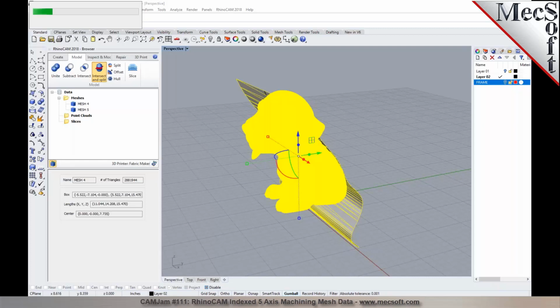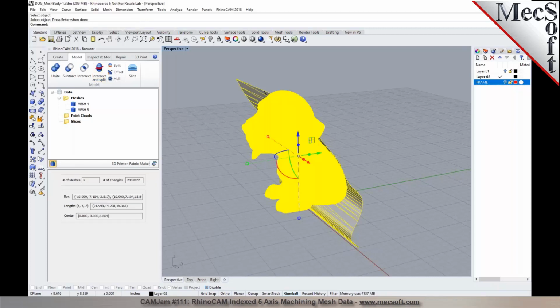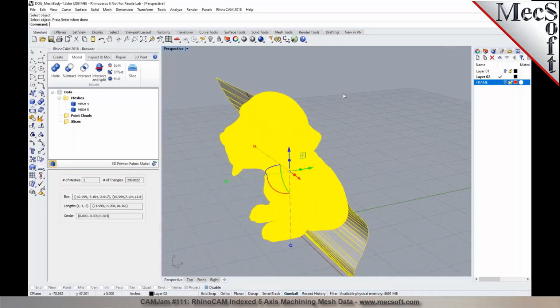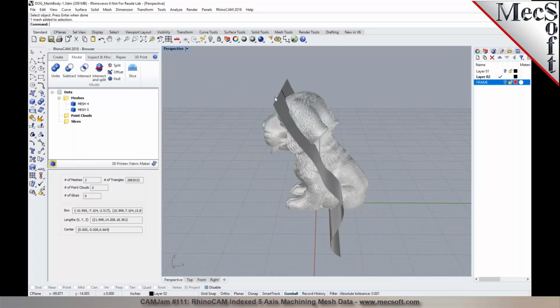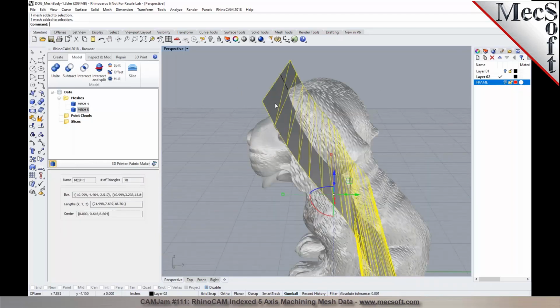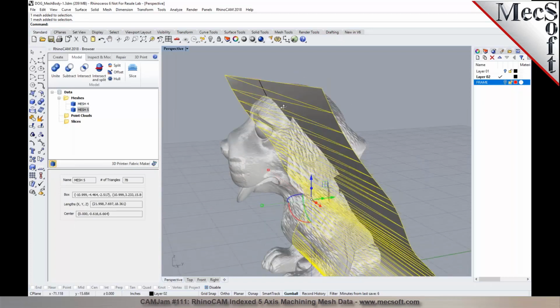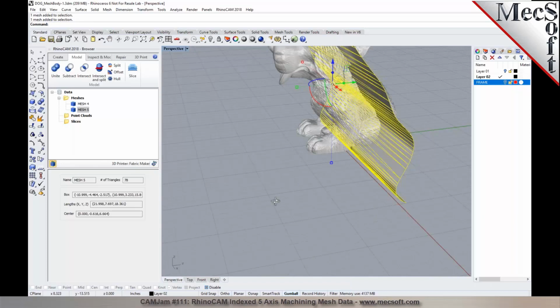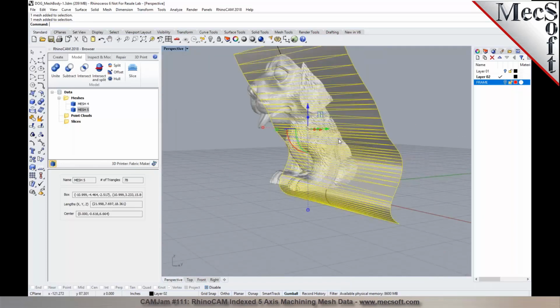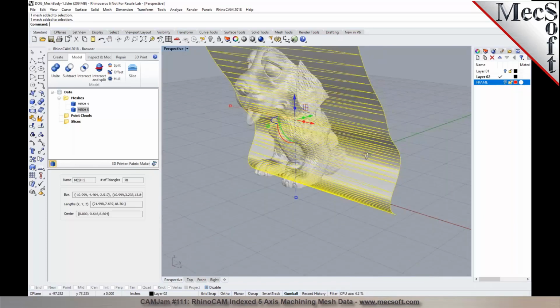So you can see that the tools that you get in the mesh module have more options for you. So I had to give it a thickness here to split it. So I can probably add a wall thickness to it, and the splitting will work. And I need to also make sure that it's going all the way through. So that's something we need to make sure, and then we can split it even with the curve, or we can do a splitting on it.